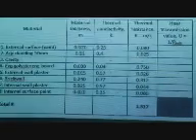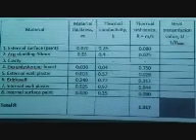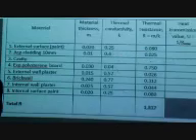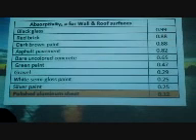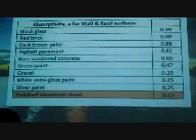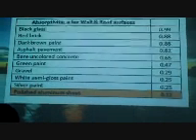And to find the U, 1 divided by R, the value of U that we get is 0.76. This is the absorptivity alpha for wall and roof surface. For this one we choose polished aluminum sheet and the value is 0.2.